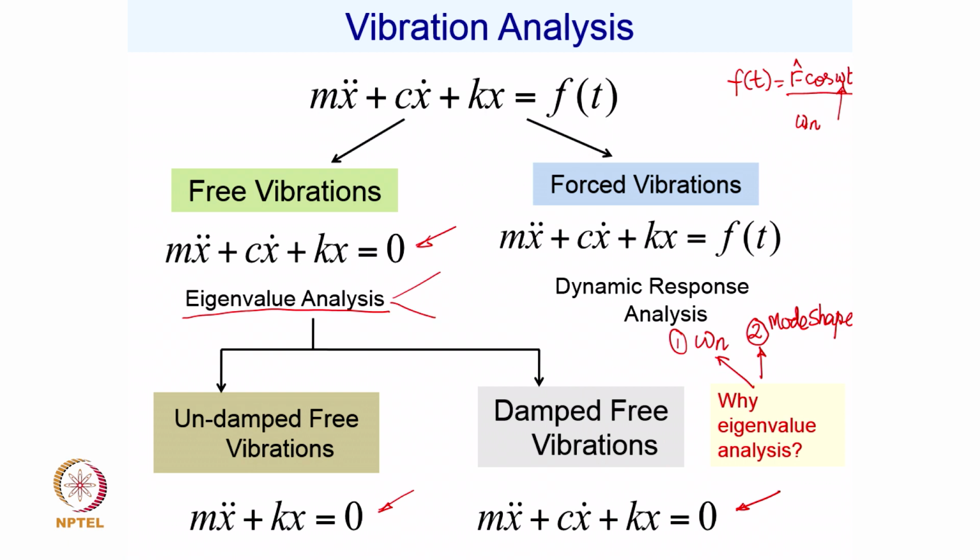In fact, when we do this eigenvalue analysis, you do get natural frequencies and corresponding mode shapes out of that process. We shall discuss mode shapes later, but since we have raised this question as to why at all we should do eigenvalue analysis, why do not we straight away go to forced vibration response and obtain x of t, is that for design approach, vibration based design, they have their own important implication or influence.